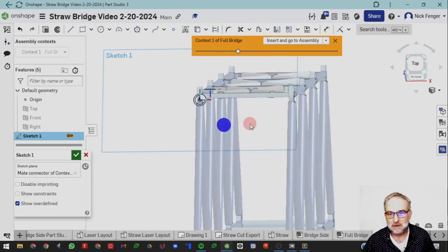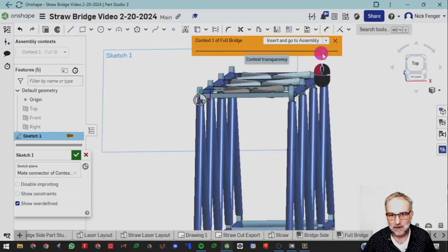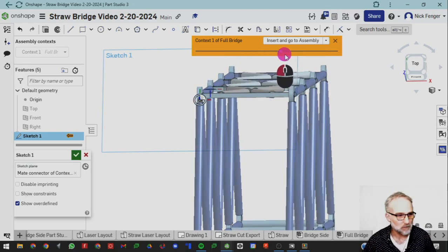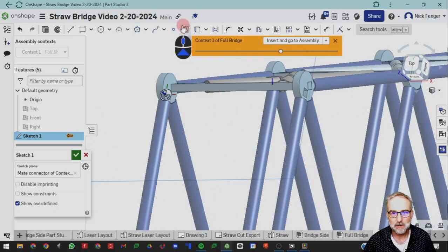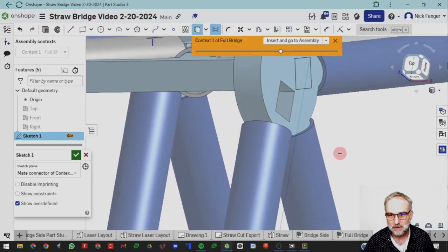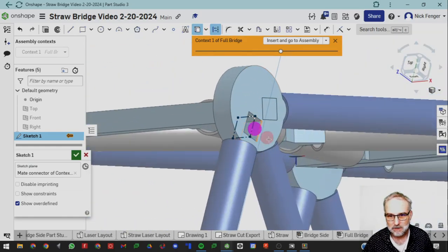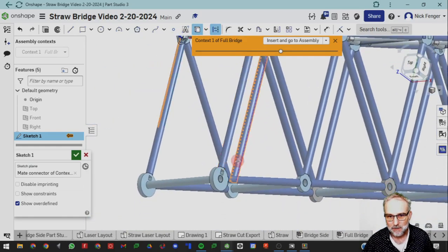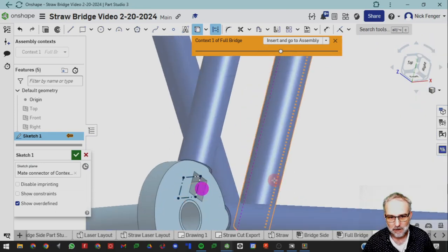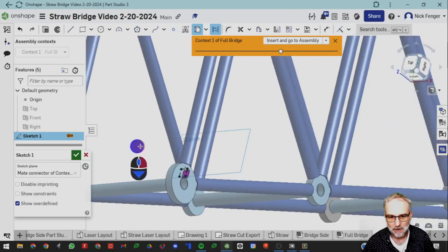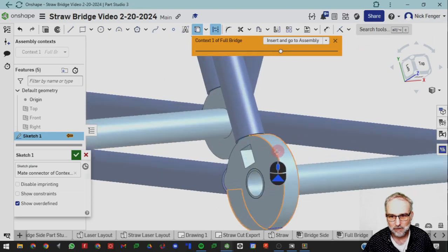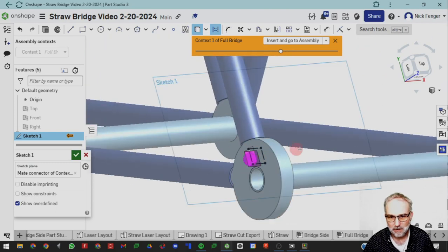So this is going to be the easiest way to get reference to our assembly. You can bring that in and out here if it's too dim for you. So first thing we're going to use is sketch lines. So we'll actually create sketch lines from anything we're clicking on. So let's just grab all these faces. That one turns purple. That one, notice it turns purple. And that's how we know we have a reference to our assembly.